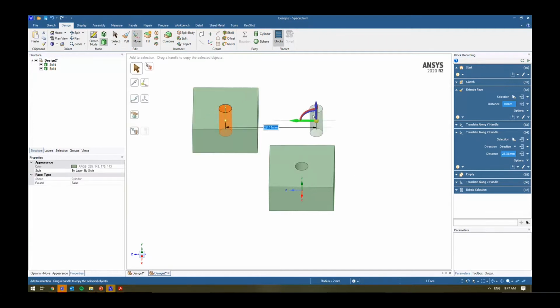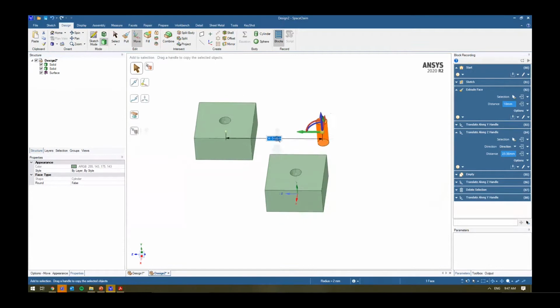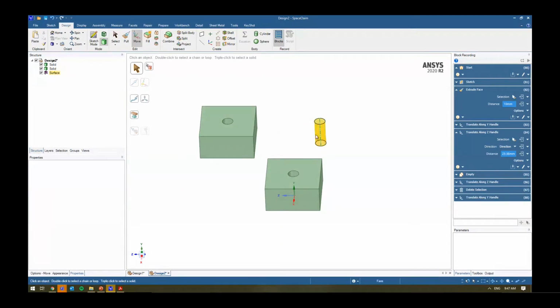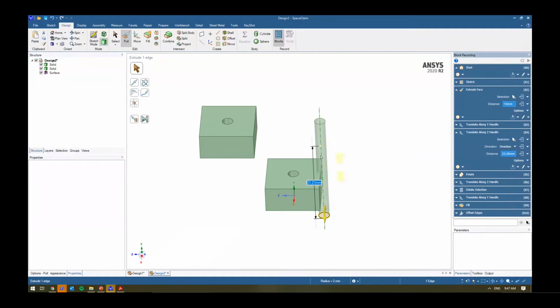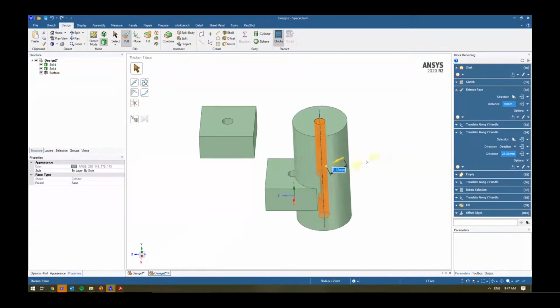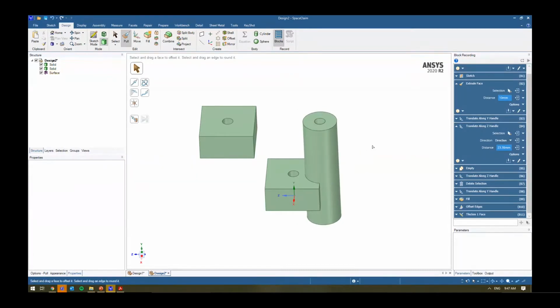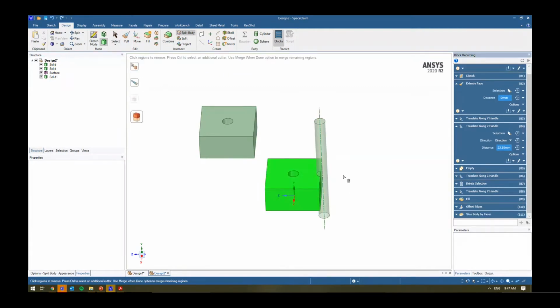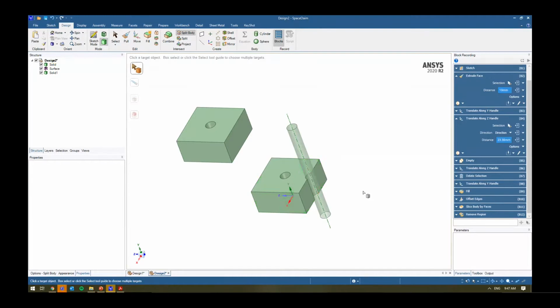If I take that surface, there you go. So instead of Control C, Control V, I can select that surface, use the move tool and hit Control will create separate ones for me, separate entities for me. Again, I can select the top, use my fill tool, can bring that, use the pull, push it all the way down. Let's just say we make this a little bit larger, right? It combines everything together. Or I can use my split body, and I can split that body using that surface there and get rid of it altogether.